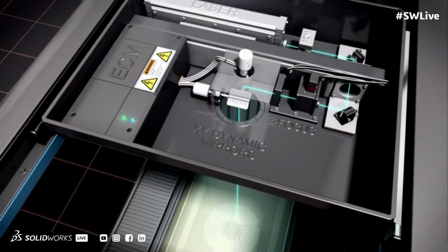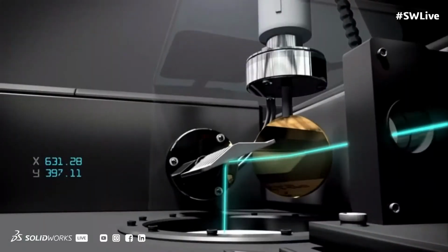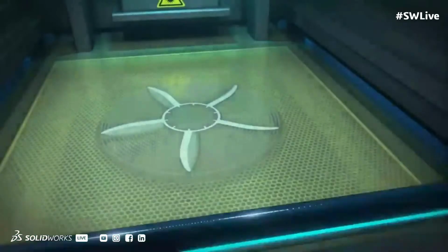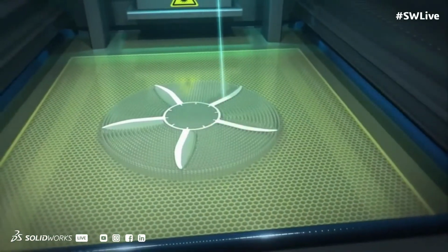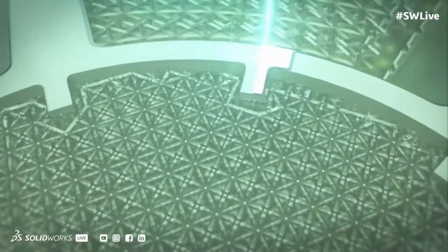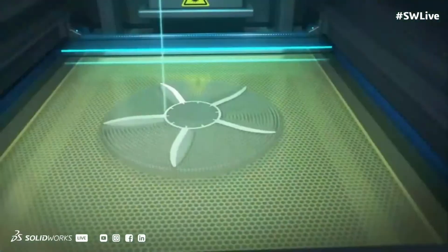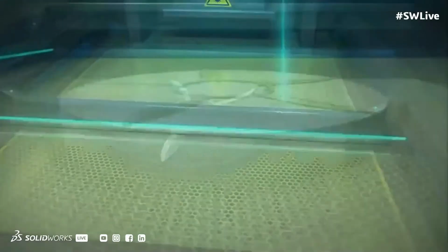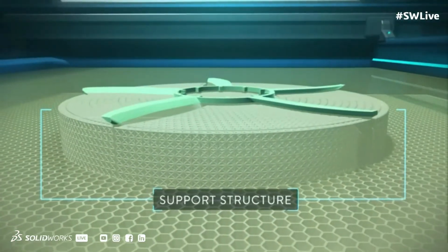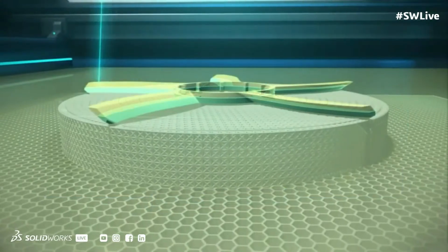So what you see here is we've got a vat full of a photopolymer, and we have a laser beam that's filtered to be a UV laser beam. Anywhere where that laser beam touches the surface of this vat, it is going to instantly harden that material because the UV light interacts and causes a chemical reaction in that liquid to harden and to glue itself essentially to the layer below or bond to the layer below.